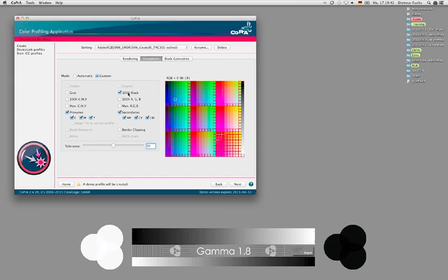You can target the way how the conversion shall be doing. And that's what basically I have used in my setting, or going back to my profile setting I've selected, you'll see that I've as well used the max RGB setting, and that makes sure that I get this maximum saturation for red, green, and blues that I had in my profile.